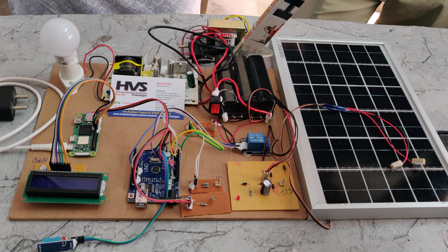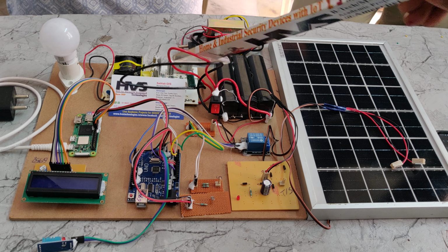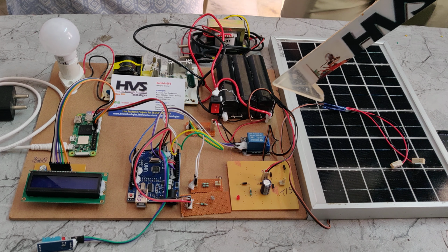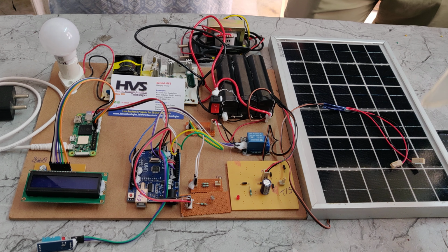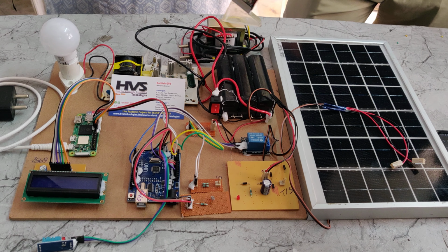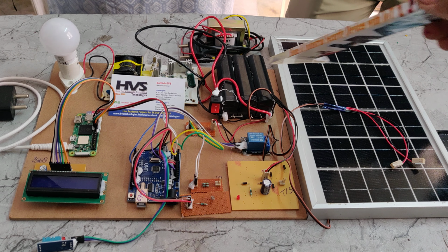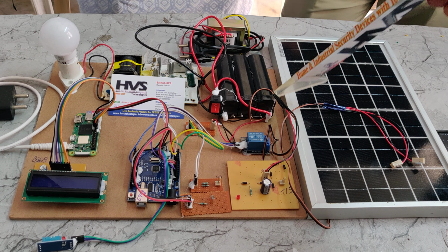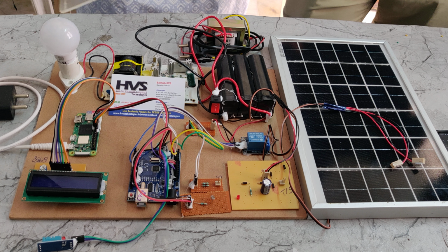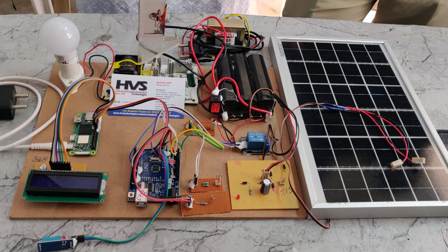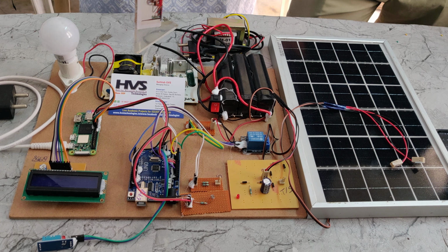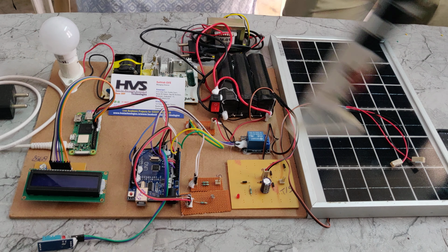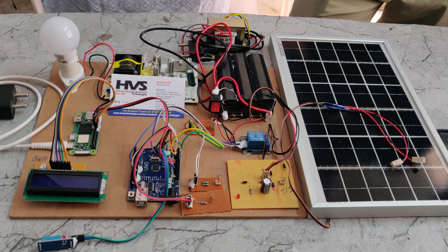This is not directly part of the project. The total system is driven by the battery pack along with the solar panel. But in case there is no sunlight, then we need to charge the battery pack with the help of this transformer. Once the battery is charged, we can utilize the power directly from the 12 volts to an AC output with the help of this inverting circuit. So it has two stages: one is the inverter and the other is a step up transformer. After these two stages, we will get 230 volts AC output.